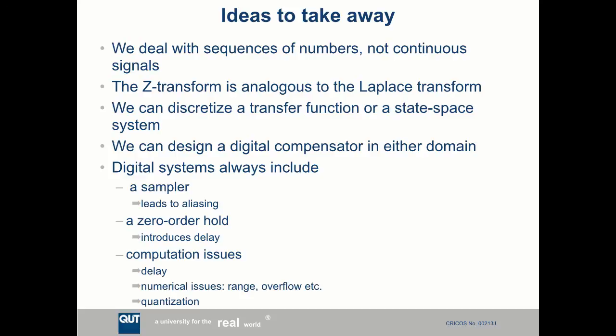Computation issues. Computation takes finite amount of time, and depending how big that time is, it may or may not impact the dynamics of your plant. You'll have numerical issues about the range of the numbers, about overflow and so on. And you'll have quantization, which we showed has interesting interactions with the discrete time nature of systems.